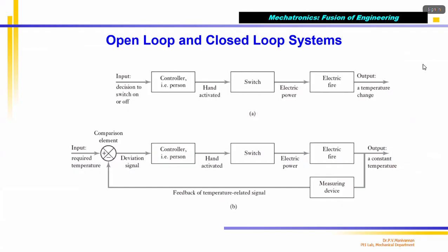To avoid that, what I do is I put a measuring device in this, which measures the actual system output, engine torque or engine speed, some parameter which is related to air fuel ratio. I measure and give the signal to the system. So the controller measures. See, you are saying inject the fuel for 1 millisecond duration.